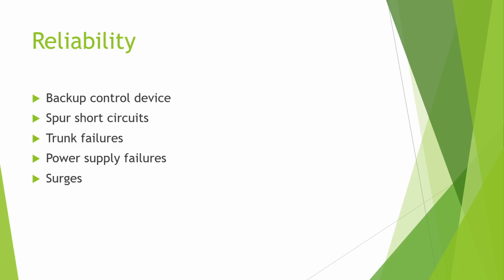Some companies will set up power supplies or pumps or things like that that you have redundant of, a backup for emergency situations like that, but they'll actually alternate between the two. And it does two things for you. One, it wears them evenly, so you don't have one that has 10,000 hours on it and one that has 1 hour on it. It also allows you to constantly be checking your backup to make sure it is working. So if it's able to switch back and forth between them, you know, yeah, our backup system's working, we're fine. It just gives you peace of mind. So that's the benefit of wanting to test your backups regularly.